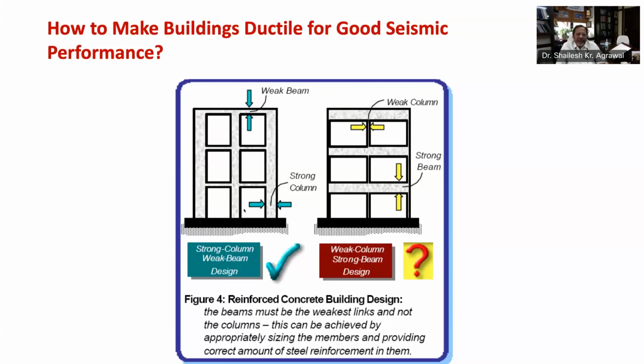But before we wrap up this tip, let me briefly dwell upon quality control in construction, which plays an important role in earthquake resistant design. The capacity design concept just explained to you for earthquake resistant design of buildings will fail if the strength of brittle links falls below the maximum assured values. The strength of brittle construction material like masonry or concrete is highly sensitive to the quality of construction material, workmanship, supervision, and construction methods. In a similar fashion, special care is needed in construction to ensure that the elements meant to be ductile are indeed provided with features that give adequate ductility.